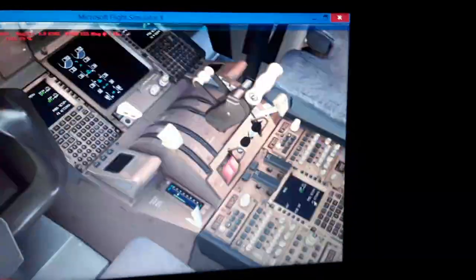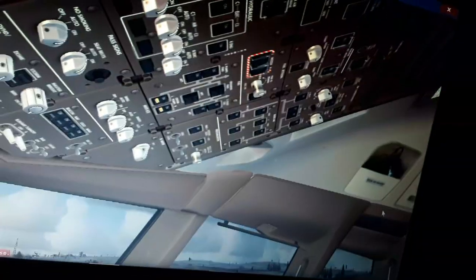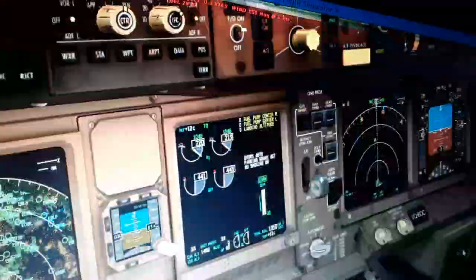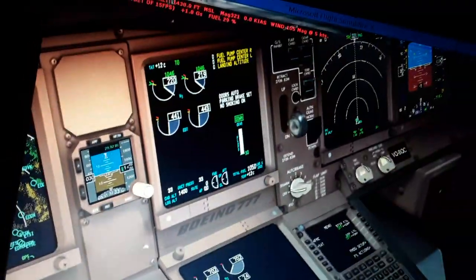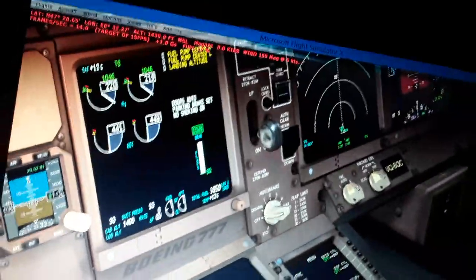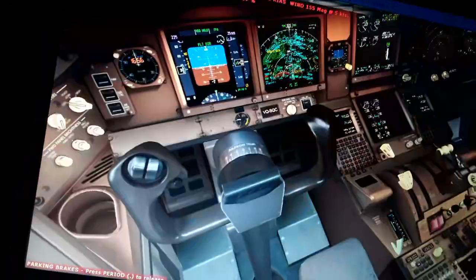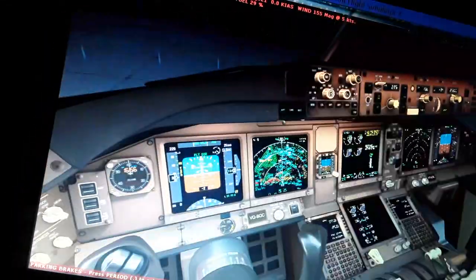using the flight control, the autothrottle system with the flight director and the autopilot, and also the autothrottle with the thrust lever position, the autopilot commands and the flight management computer input. So it has a lot of stuff in it, a lot of controllers. You can see the electronic engine control computers here with the auto start for the engines, the fuel system here. We also have the pressurized air flow from the engines for the hydraulics here, pressurization. So we have some hydraulic pressurization from the engines, also valves.